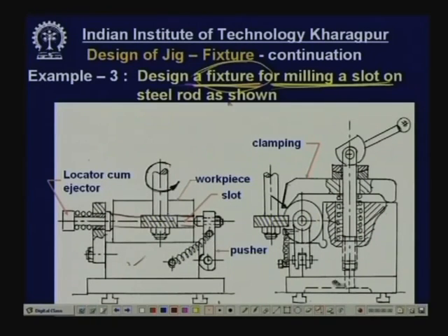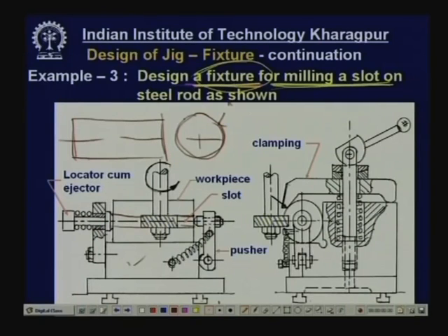Here you can see that this is the blank. Okay, this is a straight rod, a pre-machined rod with good outer surface and length, faces, all these things, periphery. So, you put it, so obviously V blocks will be suggested for locating and supporting, but since a slot has to be cut with a vertical axis, the job has to be held in this fashion and a V block will be in this fashion, not exactly like this.